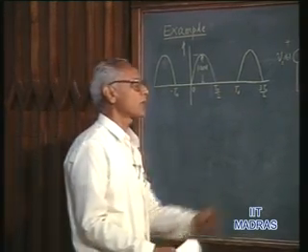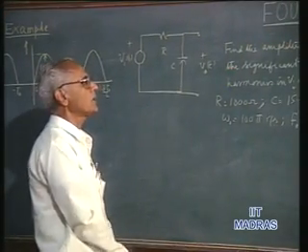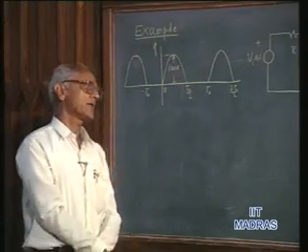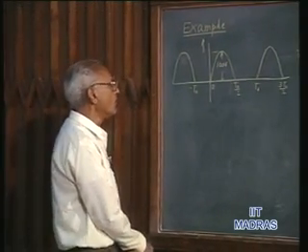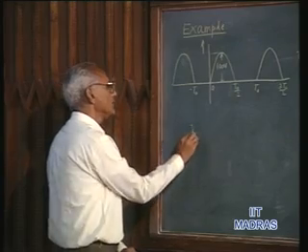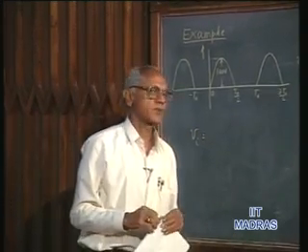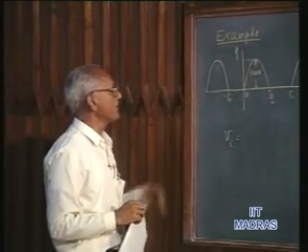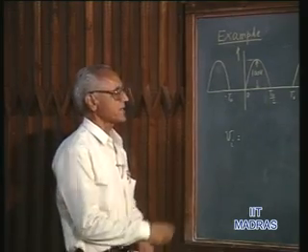Or in a problem like this, we are only interested in knowing the magnitudes of the harmonic components in the output voltage V0. So for each harmonic we can apply the phasor notation and the phasor algebra. Now we know that Vi can be expressed by means of a Fourier series, using the result that we obtained in the previous example when we considered just this kind of wave, the half wave rectified sine wave.